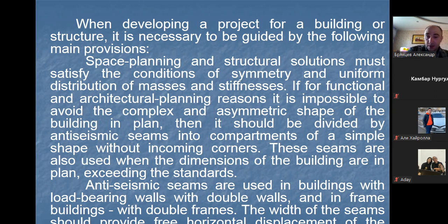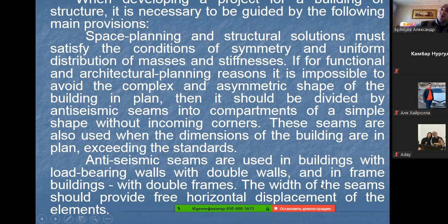Anti-seismic seams divide the building in all its constructions, be it walls, foundations, or partitions, it does not matter. Maybe on the external part of the building there will be no visual dividing of the elements, but inside the building, on each side of the seam, additional walls, columns, and foundations are installed directly, with a little free space between each other, so they have no rigid connection.